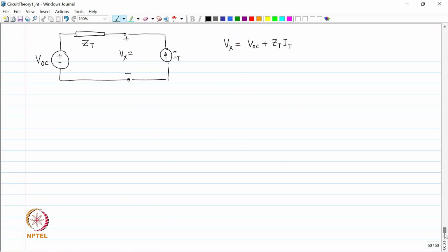Okay. So, Thevenin says that any network I take, linear time invariant, any network I take, I just measure the open circuit voltage, I call it V t, I measure the driving point impedance, I call it ZT, and the network is now the same as this, right, they are equivalent. Norton says that the same network, I measure the short circuit current, I measure the driving point impedance, and they are the same.